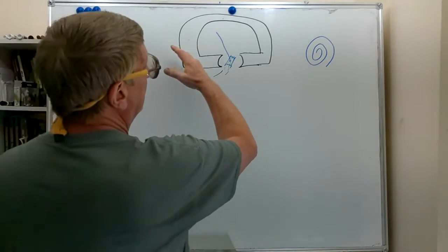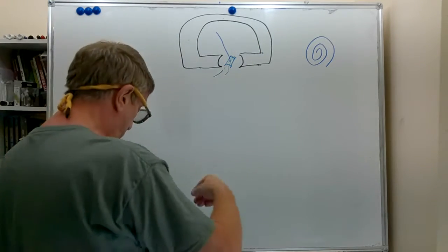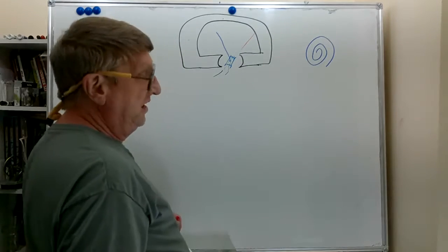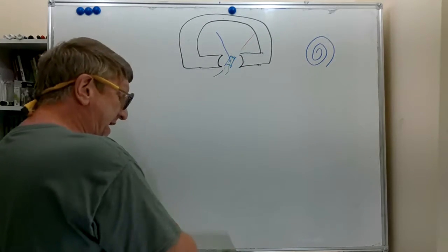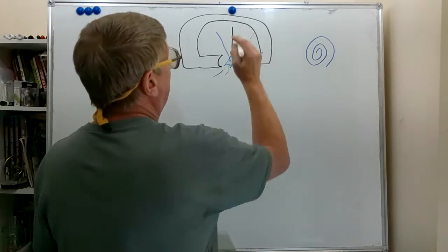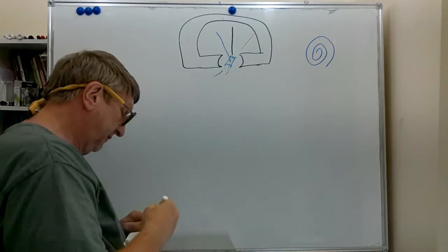If the meter was designed so it took 1 milliamp to run it all the way over here to full scale, if you had half a milliamp flowing through that meter movement, you would have a half scale deflection of the needle.